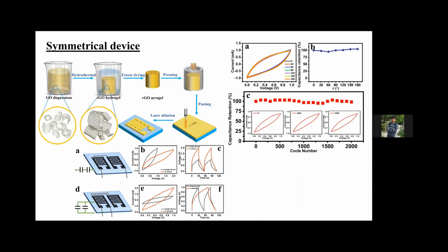Here we can see it: we can bend our devices and check the performance at different bending angles. We need to make sure that across many different bendings, the capacitance retention stays the same, because degradation is not suitable for wearable devices.